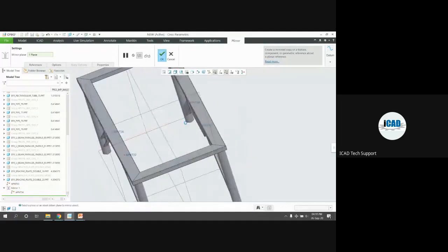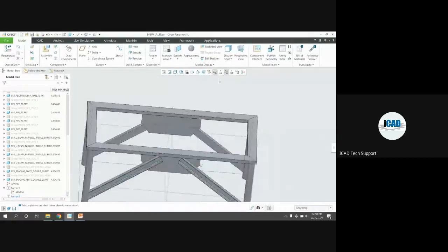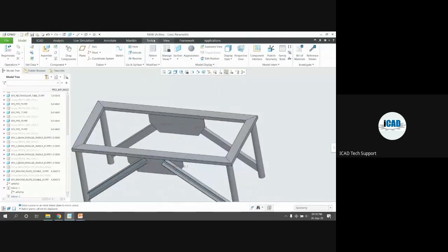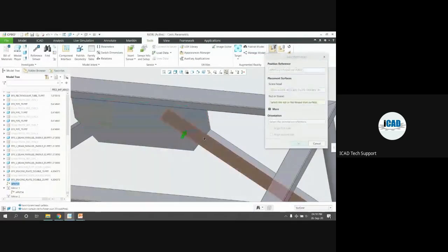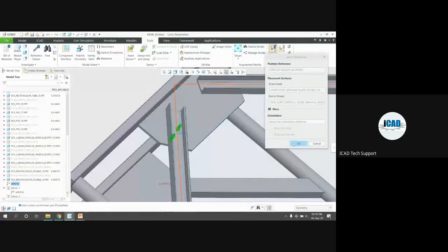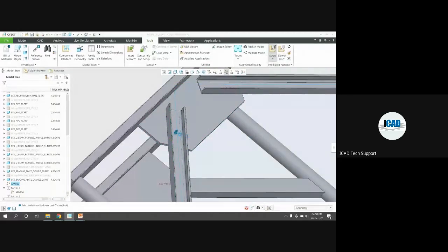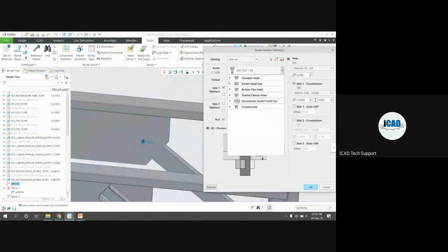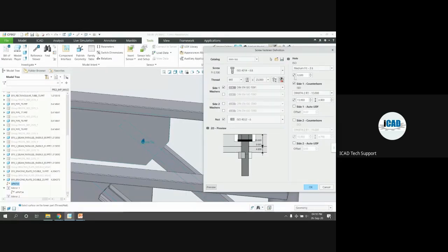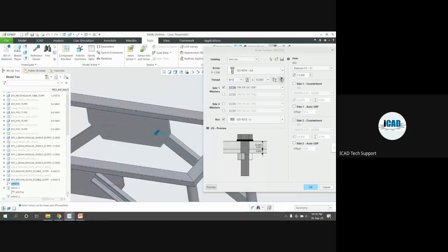You can see. And here you can apply the fasteners from the toolbox. Click on the bottom surface and click on the back surface. Click on OK. Now you can see you can change your standards to a hex bolt. You don't want to add the counterwork, just select here and enter here M10 size. Click on the automatically set size.